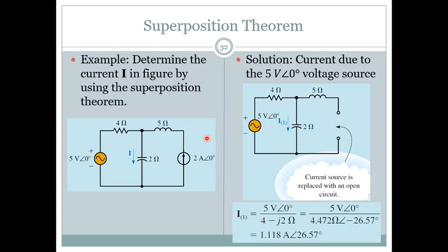In this case you have to consider each source at a time, but the calculations will be done in the complex number domain, because in general all these parameters have a magnitude and a phase angle, or they will have imaginary components. So if you consider only V, the voltage source, this is removed, so there is no effect from this side.